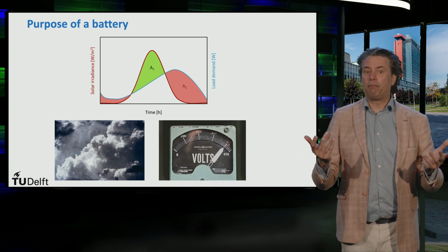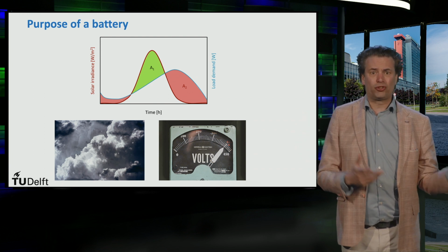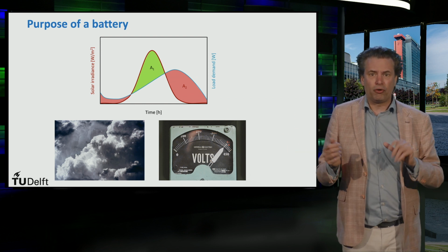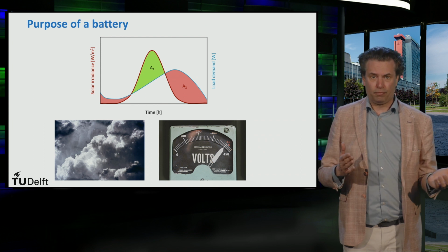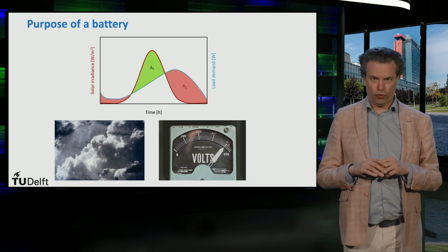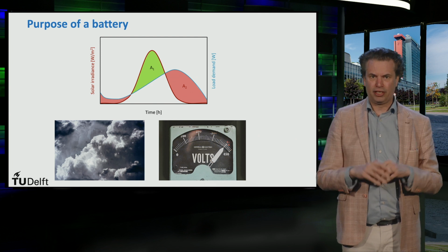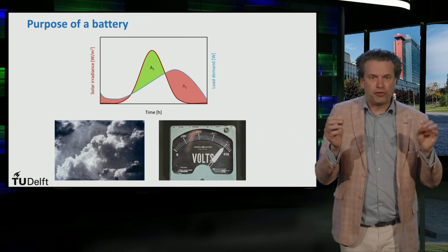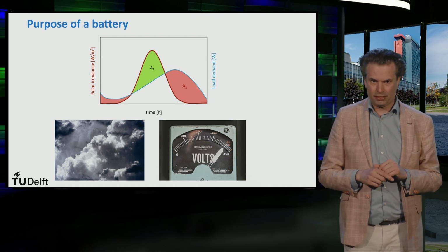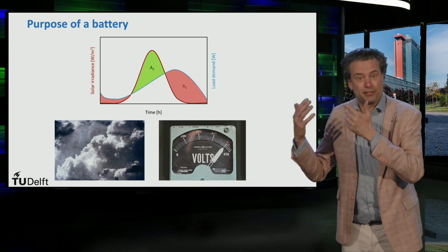You are well aware by now of the IV curve of a solar panel. You also learned that if we connect a solar panel directly to a load, the voltage will change depending on the demand of the load, and this will be very difficult to control. Batteries, on the other hand, are quite easily simulated by a constant voltage source. This essentially defines the system voltage. There might be subtle changes to the voltage, but a battery acts as the bedrock for the voltage of an off-grid system. This is not the case for a grid-connected system, because in those systems the grid itself supplies the stable voltage.